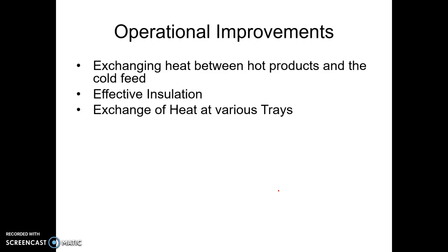However, there can be a limit. There should be a limit to doing this, right? Because we cannot have an exchanger at every tray. So hardly one or two additional such exchangers you can add. But if that is going to be beneficial in terms of utility cost, we should think of doing it.